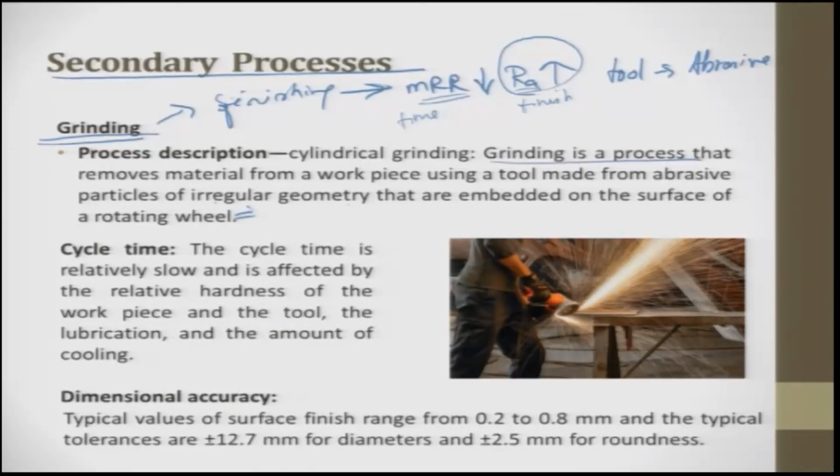So, the wheel speeds, generally today we talk about 1 lakh RPM easily, but in general what we talk about in lab scales, academic scales, or in machines whatever you get today is 1000 RPM to 5000 RPM. Like handheld, you can get up to 5000 RPM. See, 1 lakh RPM, it has to have a stable, rigid structure. And generally, from the designer's perspective, we have handheld grinders which rotate at speeds between 1000 RPM to 5000 RPM. It's pretty high. So, that is why when we try to grind, we try to hold it with 2 hands and then start doing it.